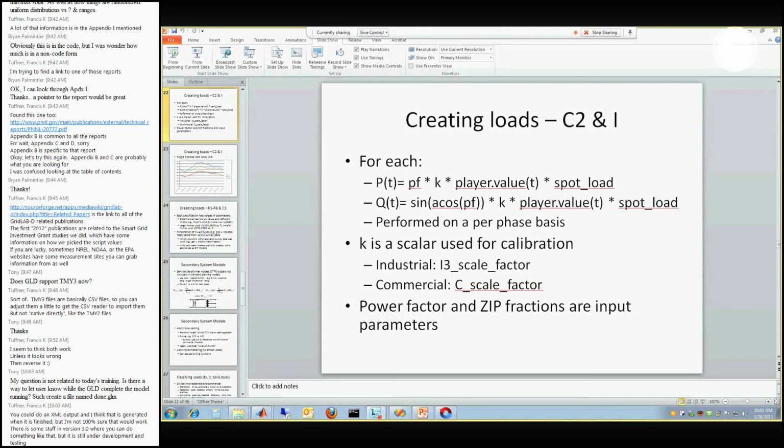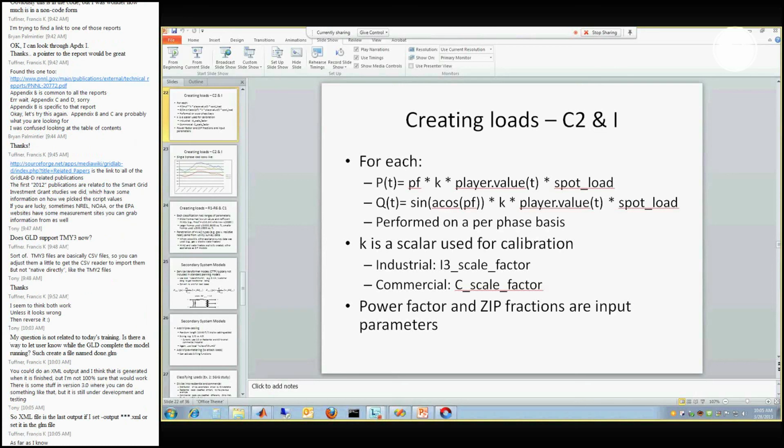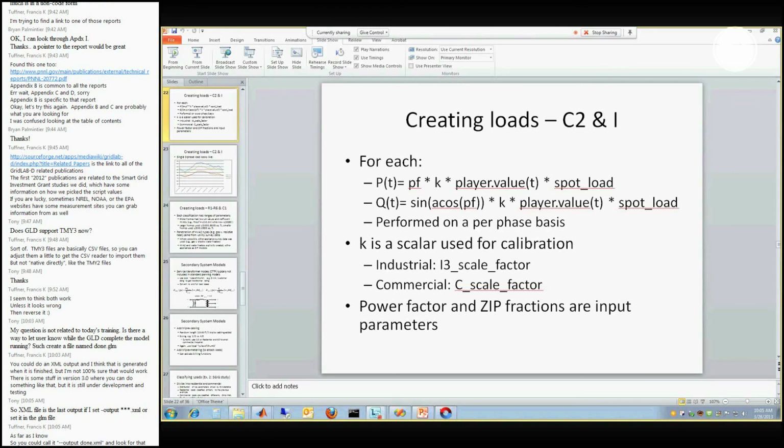Especially if you're using your 4-quadrant control rather than just real power output, you can affect voltage a lot quicker and a lot easier with your reactive power than with your real power. If you've got energy storage, you've got a lot of options. But even with just the 2-quadrant off solar, you can combine it with some forecasting to do some ramping down. Yep, absolutely.